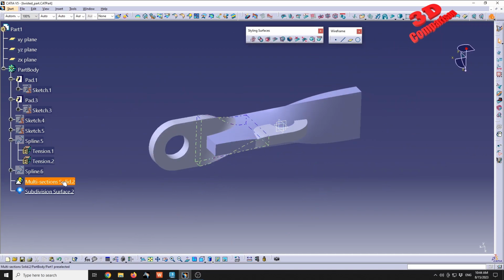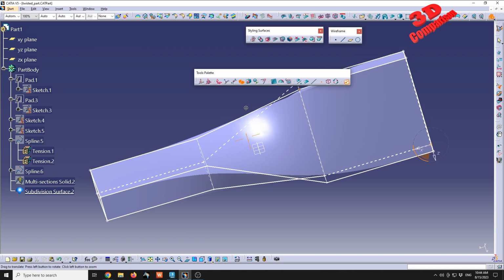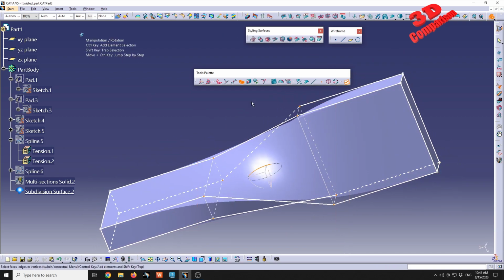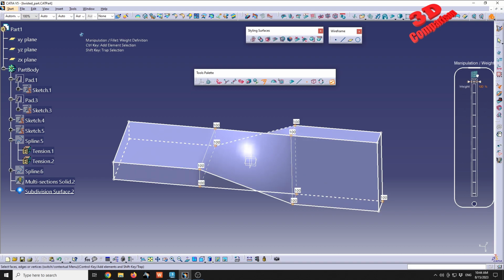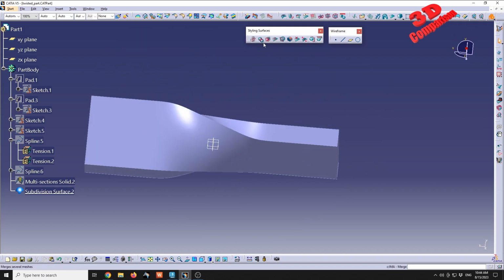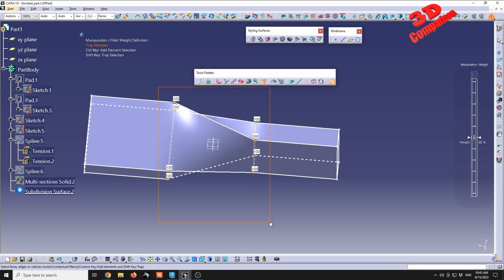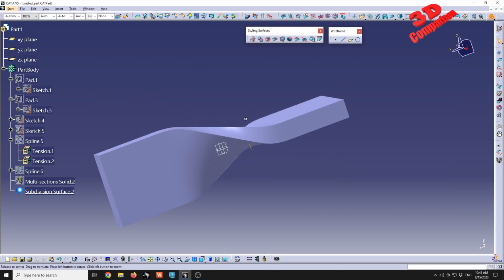But now, within the Imagine and Shape workbench, we can select those middle points and go to the attraction, and in this case the weight is set to 0, but as you can see, if I increase that, this will change that handle tension within this workbench. So if I go to 100%, I will see that the twist will look like this, and by default this is set to 0. So that's how you can adjust that curvature tension. I will leave it like this for now.